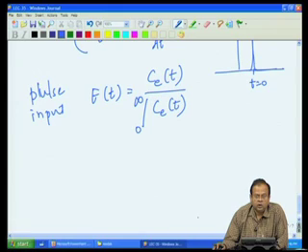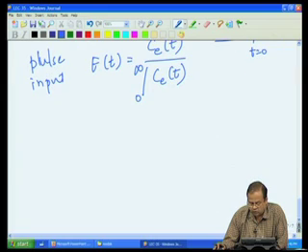To do that, I must be in a position to determine from a model what exit age distribution or cumulative age distribution I expect, and then map it with the experimental results, so that I will have an equivalent model for my reactor. We will take one or two examples to see how it works.